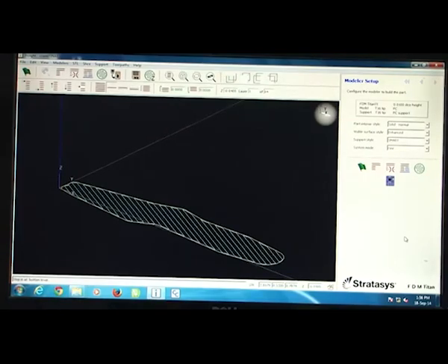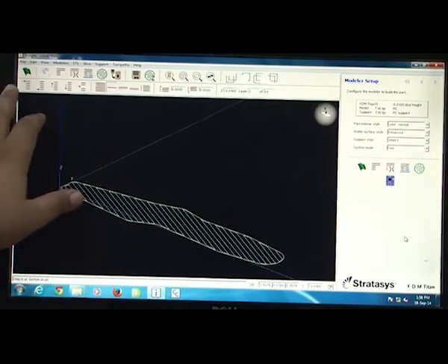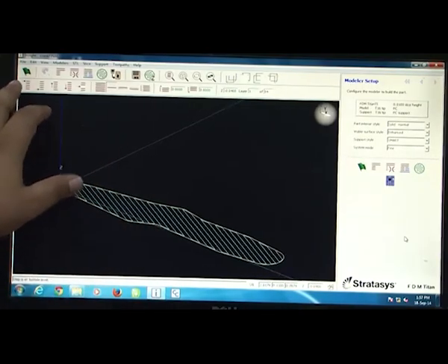fitment of the component within the volume of the box, we did various options to it. First of all, we tried to define the material. We wanted to define the slice height and the tip size. These things were selected. Once that was selected, then we are ready with the next step, which is the slicing option. So we go to the slicer menu, and then slice it into these 250 microns. You can see the slice slot coming out by going to the logo here in the top left corner, which says from top to bottom.